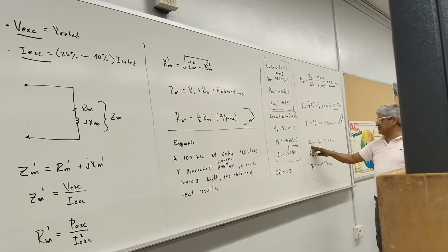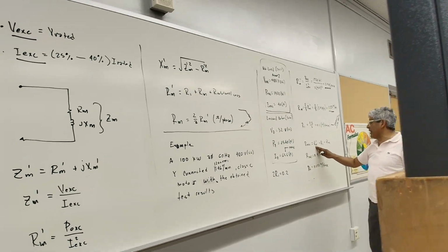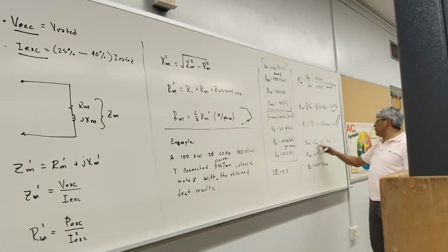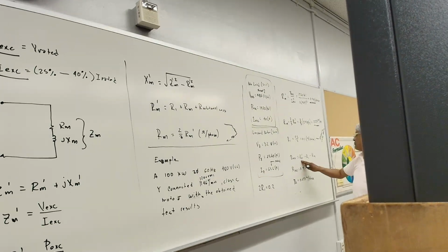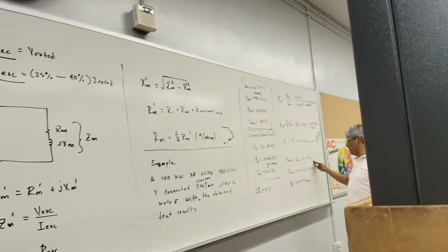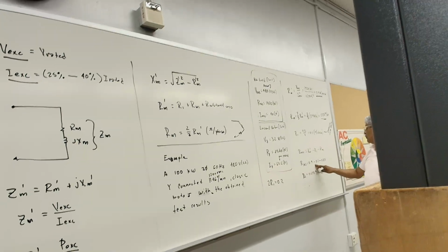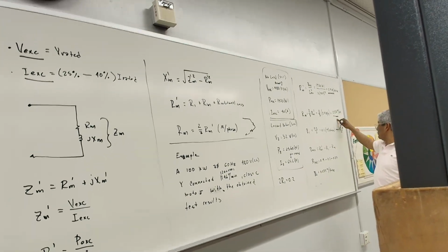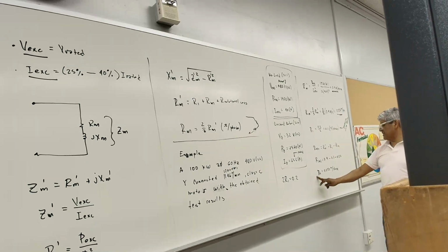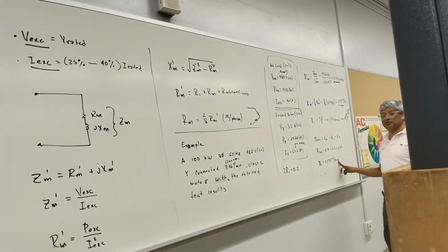The R rotational, these are the losses. So how do you compute the rotational losses? It's Rm prime, which is the excitation branch, minus R1 minus Rm. So in our case, 0.4 minus 0.1 minus 0.27 gives us the rotational losses of this machine at 0.033 ohms per phase.